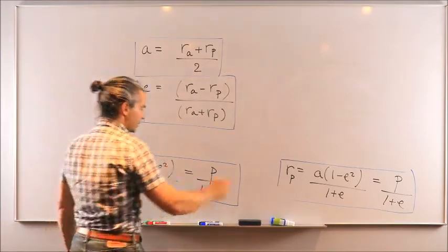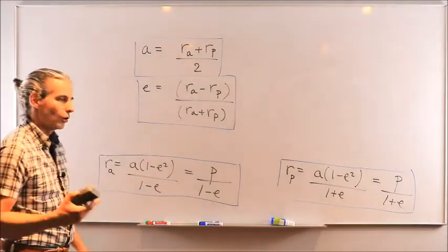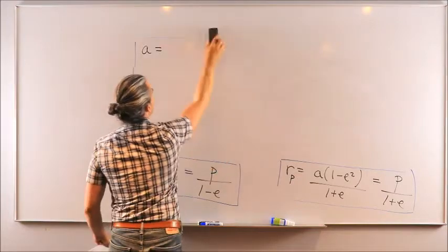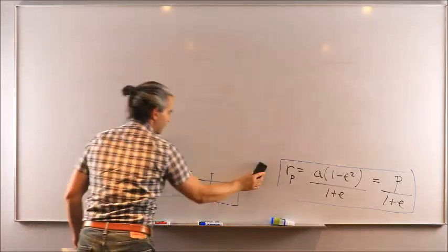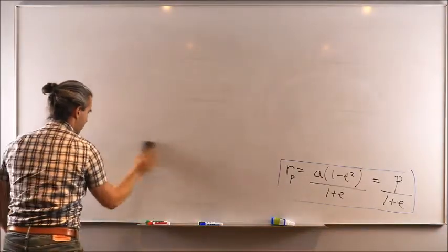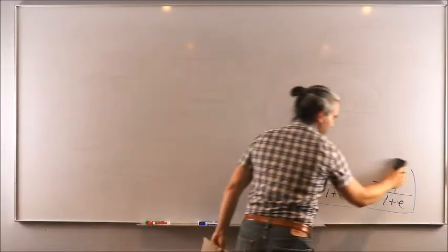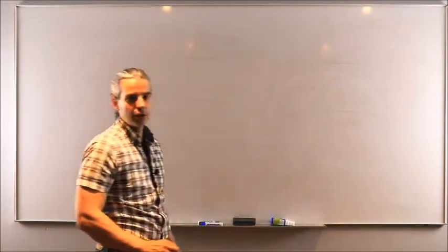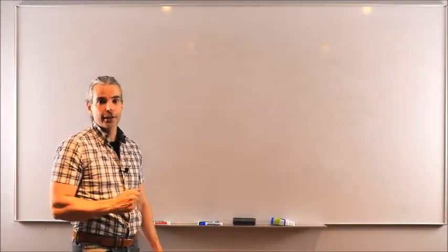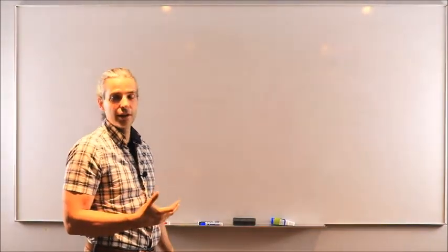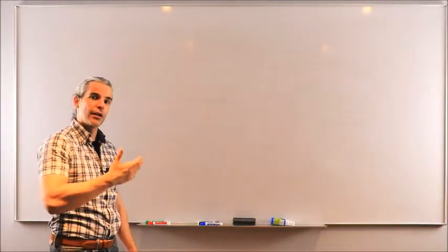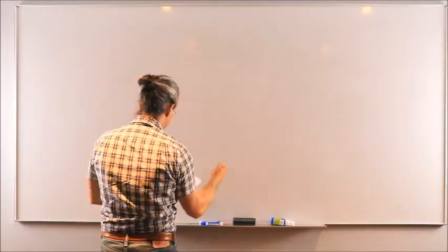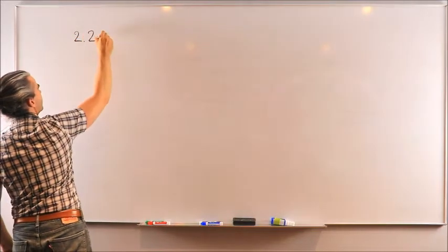All right, so that was subsection 2.2.1, elliptical orbit, which is the most generic conic section that arises through the orbit equation, which describes, as I told you earlier, any conic section. So the deciding factor about which conic section is going to be generated from the orbit equation is just selecting the eccentricity value. If it's equal to 0, this is a perfectly circular orbit. If it is larger than 0, yet smaller than 1, then you're going to generate the elliptical orbit that was just analyzed. So let's have a look at the second most useful type of orbits.